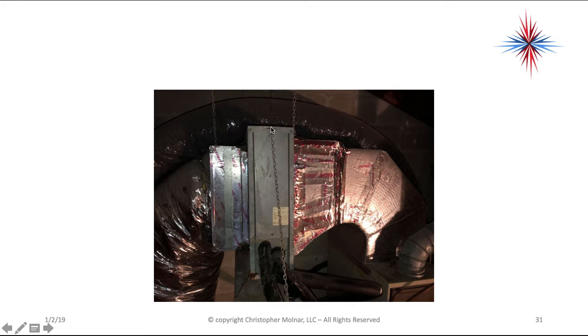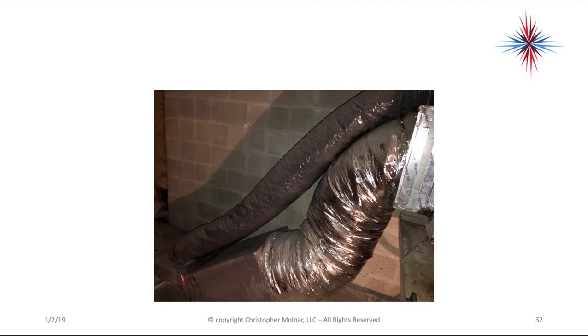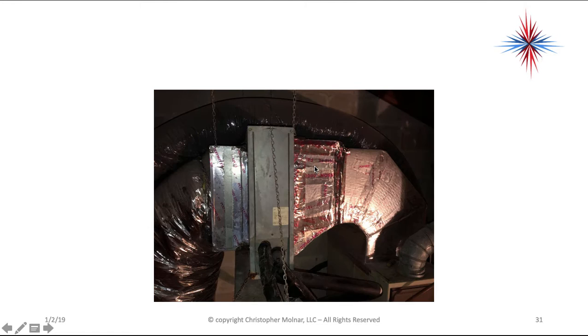The other issue is I have an air duct that is looped over here to feed some registers on this side, and I'll show you more of that in a moment. Okay, so we come out of our air conditioning coil right here, we go into a round, and then we transition back to fiberboard plenum. And again, here's that one poor duct that comes back all the way up that way.